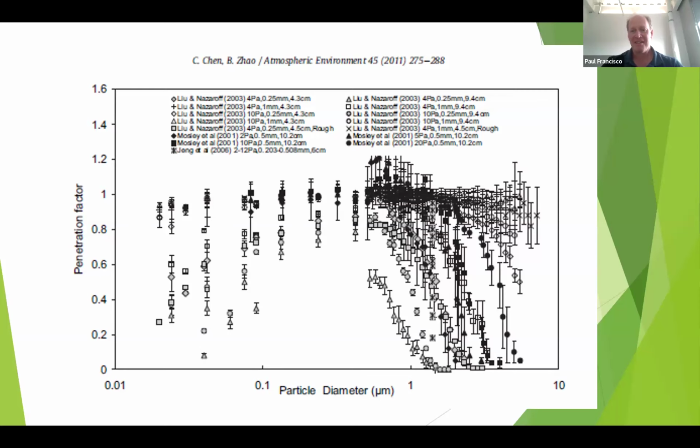So when you're talking about the major effects on particles above 1 micron, when we're talking about smoke particles, they're going to sit right in the middle of this, between 0.1 and 1 typically. So it's 300 nanometers or 0.3 microns is a good number to think of for smoke particles.